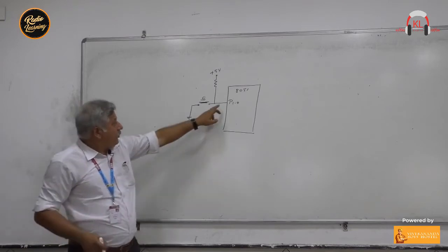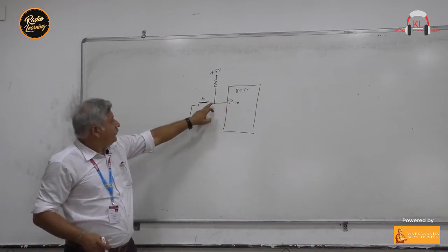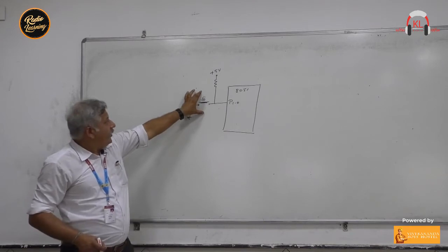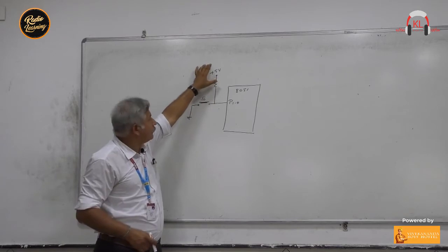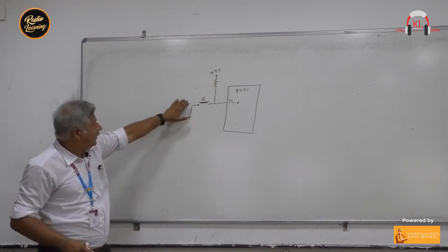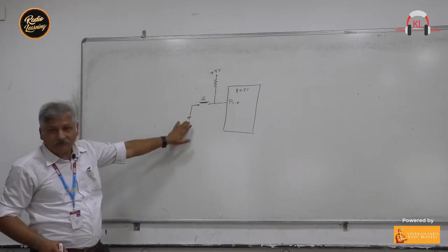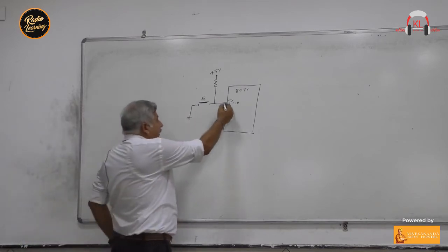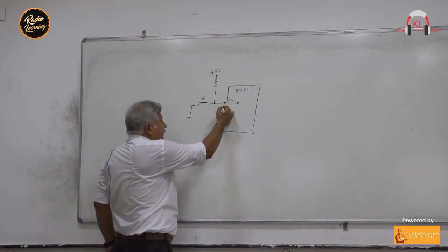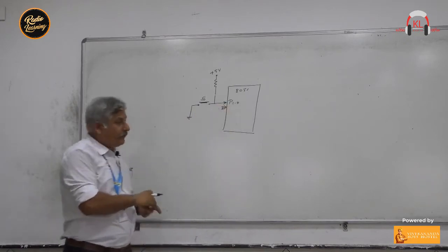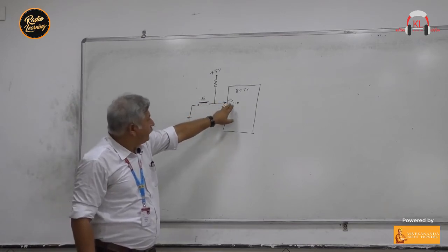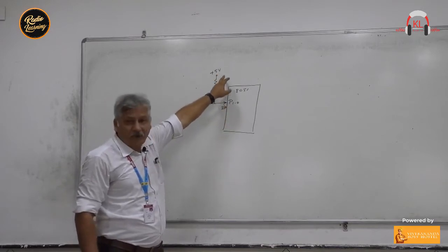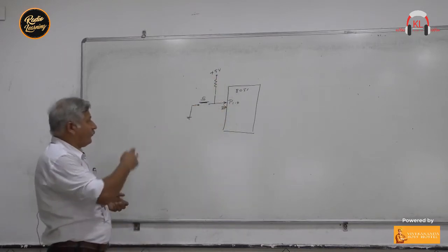So now this switch is connected. This end of the switch I have connected to plus 5 volt through one resistance. The second end of this switch I have connected to ground. So right now, if this switch is an input switch and we have not pressed the switch, then if we read the value at this pin, you will find plus 5 volt. Right?